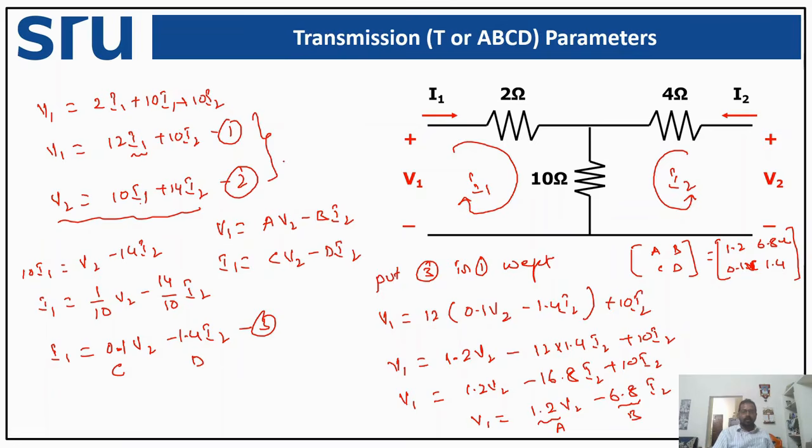And remember, we are going to discuss the conversion of one parameter to another once our S parameters are completed. Also remember, when we have a pi circuit, we can compute the y parameters and convert into our required parameters. So for a T network, compute z parameters and then convert. If we have a pi network, find the y parameters, then convert.